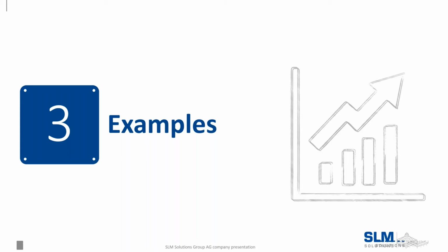So this is a D-Light system. We have used the D-Light system in the past. It's a very nice system to use, basically dry electropolishing, and it's reduced the Ra down to below 2 across the entire part, while still maintaining most fine features. That's another thing: fine features, maybe 90-degree edges and things like that, might be knocked away during a surface polishing or electropolishing technique, and we need to know if those 90-degree or fine, sharp features need to be maintained throughout the process.